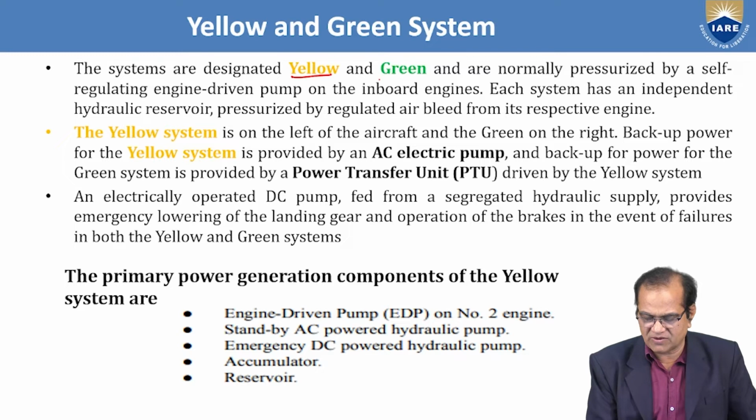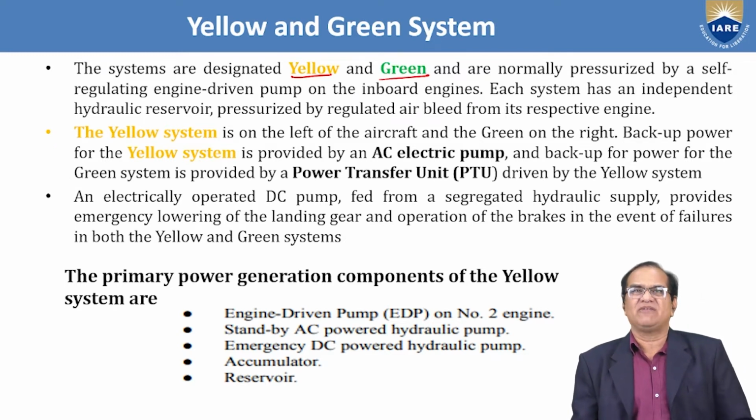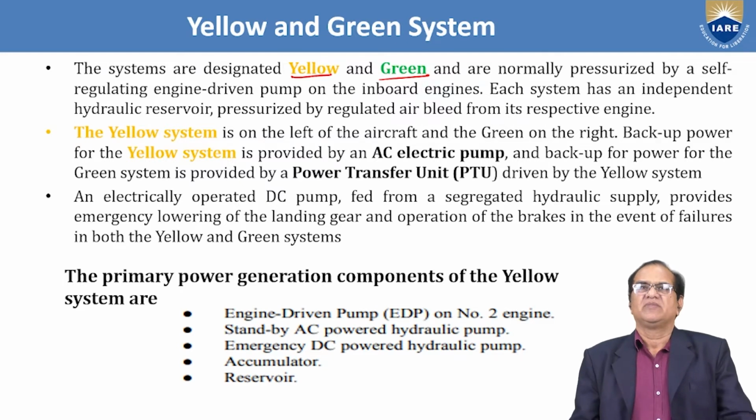The two systems are normally pressurized by a self-regulating engine-driven pump on the inboard engines. Each system has an independent hydraulic reservoir pressurized by regulated air bleed from its respective engine.